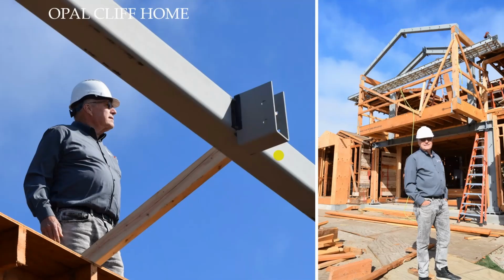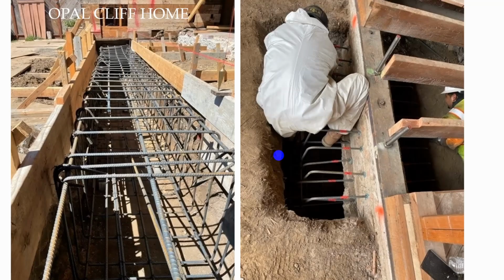So this particular project, you can see the steel moment frame there. There's a lot of steel and a lot of concrete because it has a lot of glass. Let's click to the next slide. Here's a concrete beam to take the moment frame, all the force on that. We had a whole bunch of underpinning everywhere. Sometimes when you do these remodels, they're in a 5.5 foot deep hole all day long for weeks underpinning this stuff. Let's go to the next slide.